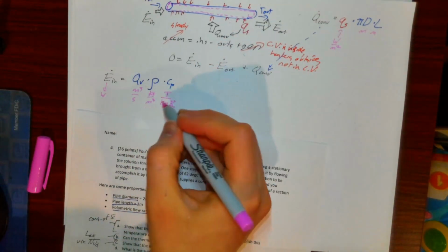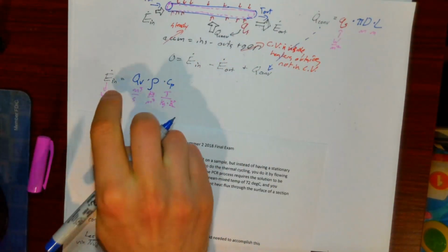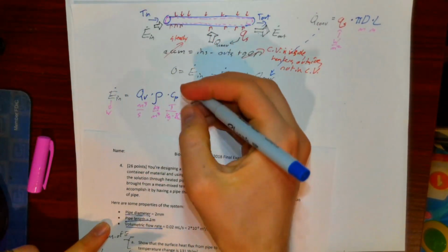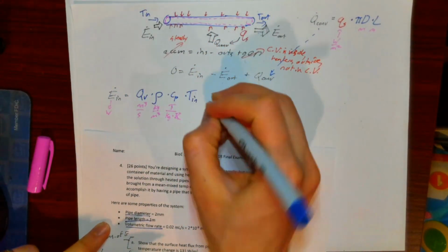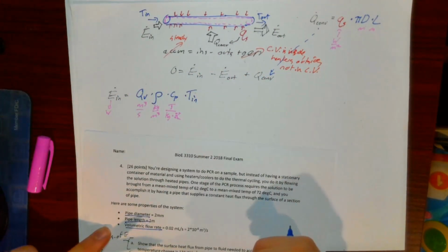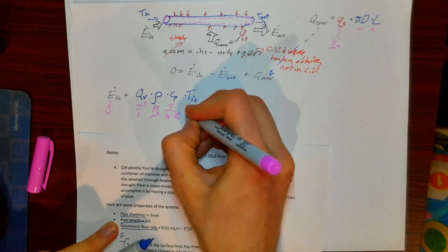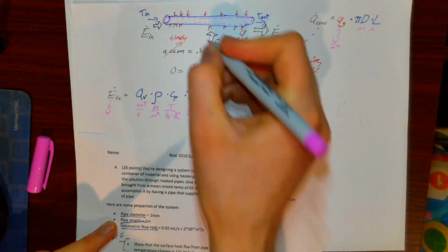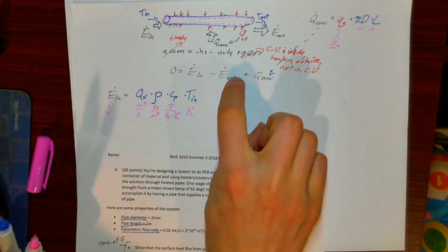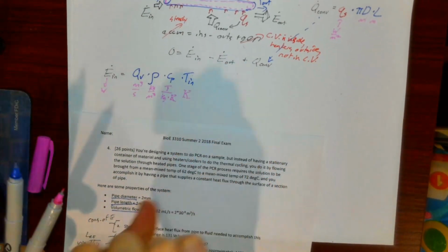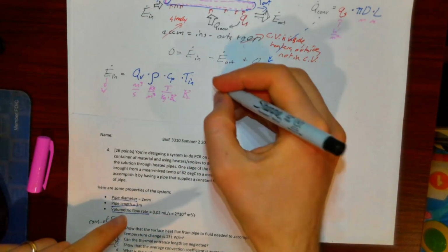And we see we're getting awfully close here. And then, of course, the thermal energy carried by the mass in is proportional to its temperature as well. So we can basically say that's the flow rate of energy carried by mass at the inlet. And I could do a similar thing with the outlet. The only difference would just be T out right here. So I can plug that in as well.